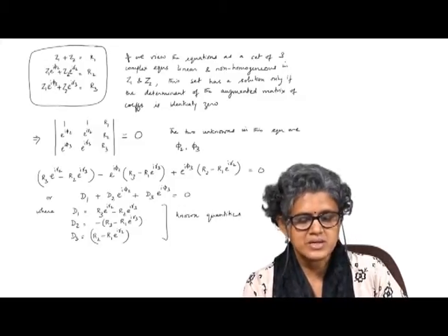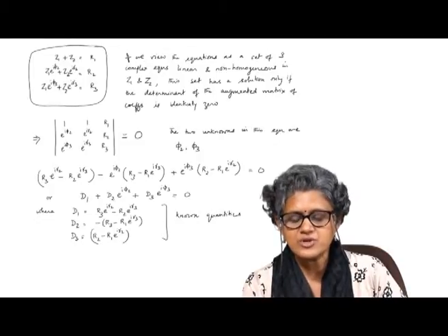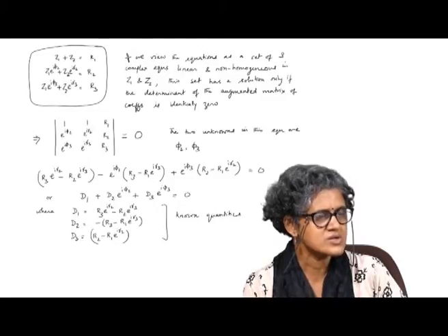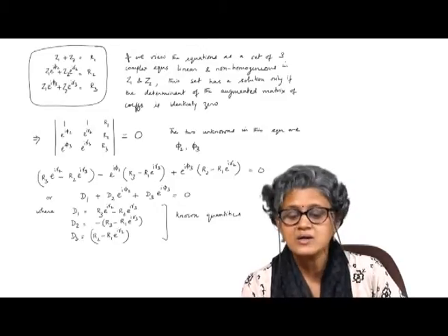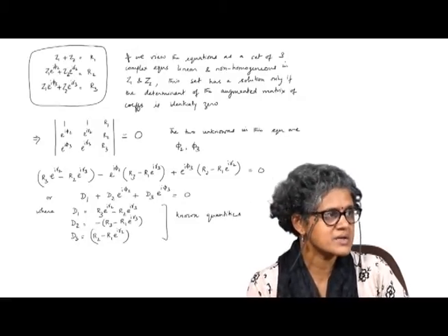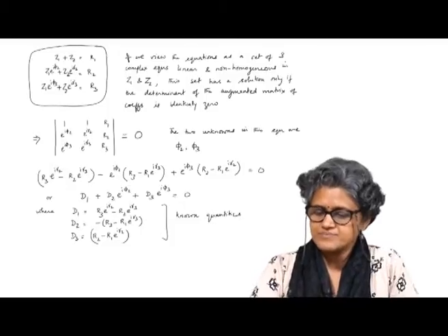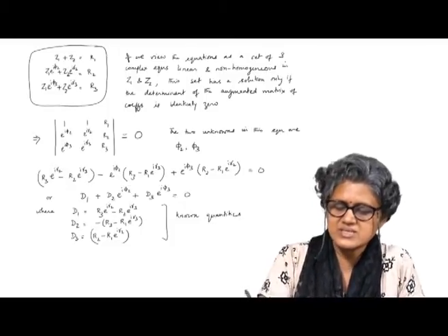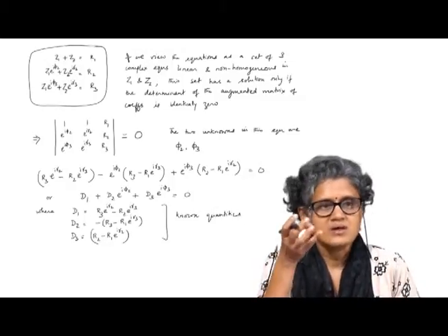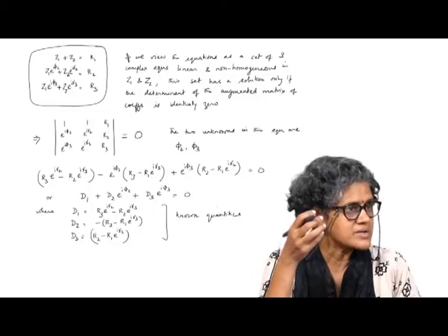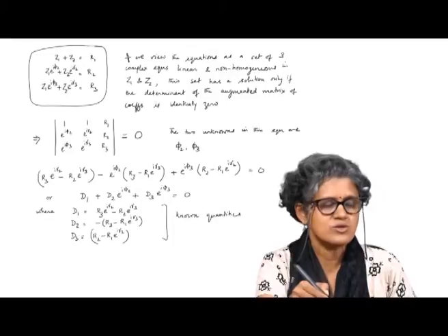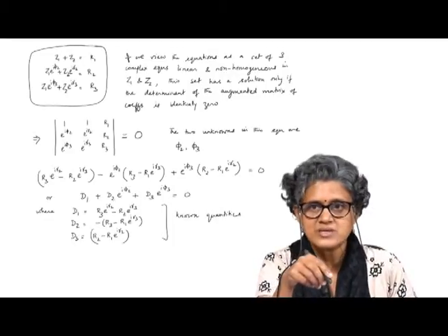In this compatibility equation, if you look at it, it is a transcendental equation in phi 2 and phi 3. So, it is not easy to solve, but we can solve it geometrically, because it is like a loop closure equation. You look at e power i phi 2 and e power i phi 3 as rotation operators. Remember we have been using that as rotation operators all along.